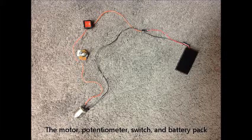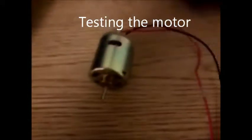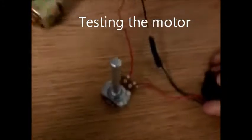After a trip to Radio Shack, we soldered together a 1.5 to 3 volt motor to a potentiometer so that we could control the frequency of the motor and thus change the size and shape of the bubbles. We soldered that to a switch and then to the battery supply, and we used 2 AA batteries to power the motor.